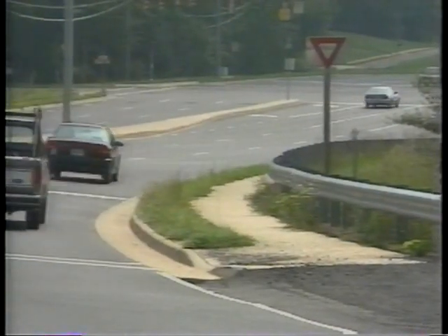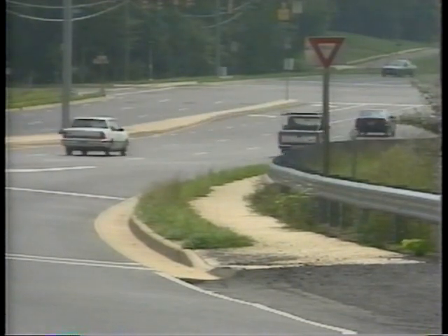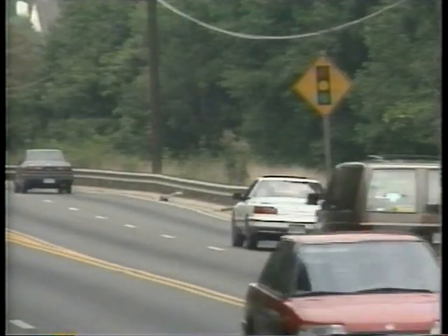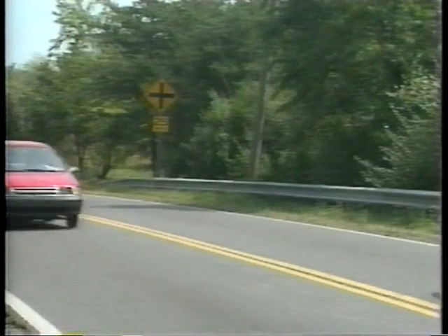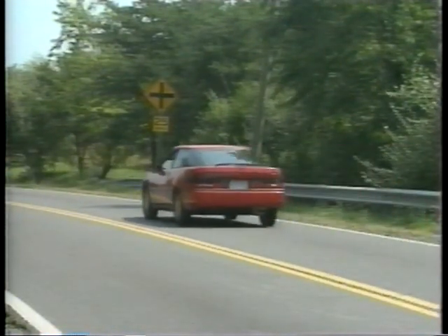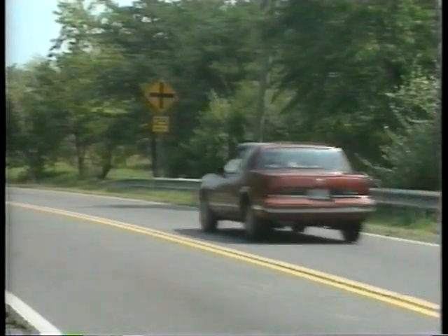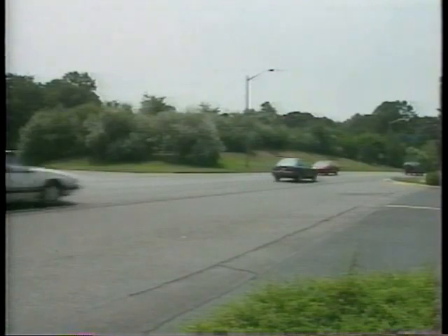These signs are used when a minor road intersects a major one, and the safe approach speed in the minor road is greater than 15 kilometers per hour. The signal ahead sign is used when a driver cannot see at least 2 signal indications. The crossroad sign is used to warn of an obscured crossroad intersection. It normally is not used if the intersection has other route signs.